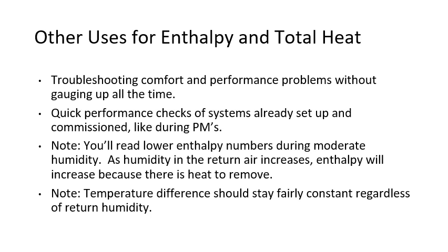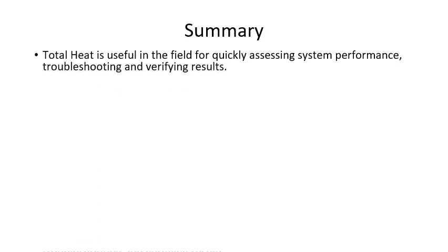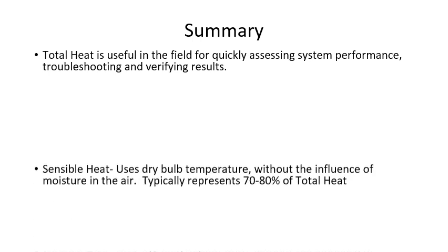So typical supply return temperature drop is between 17 and 25 degrees. The system should be able to do that regardless of humidity. So when you combine those two checks together, you can have a pretty good idea about how a system is performing. So in summary, total heat is very useful in the field for quickly assessing how a system is performing. We can also troubleshoot and verify results. And all of these are non-invasive tests without having to hook up gauges to a system.